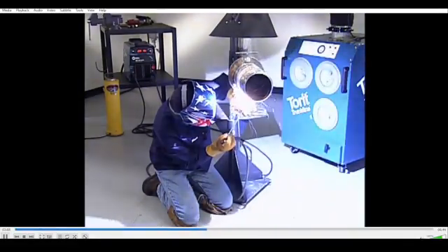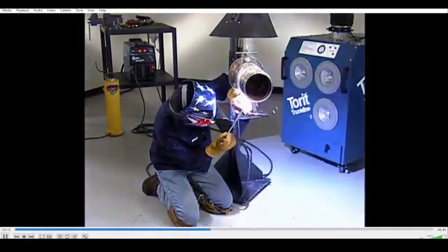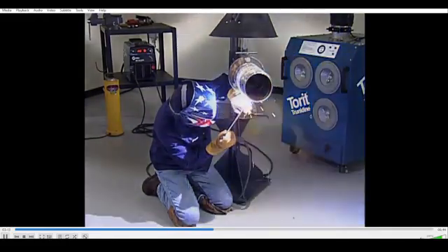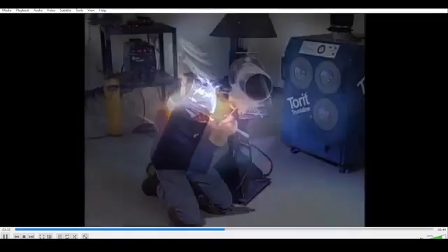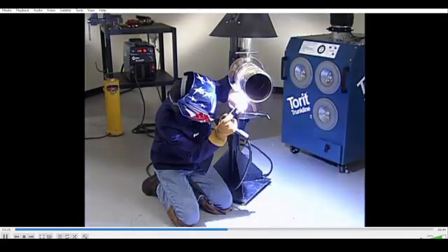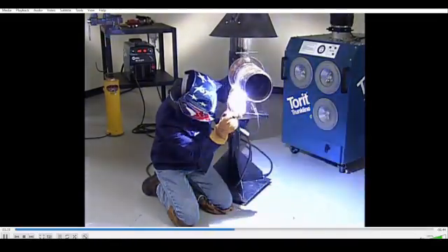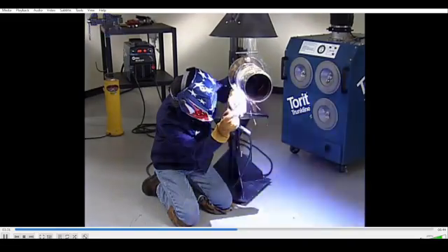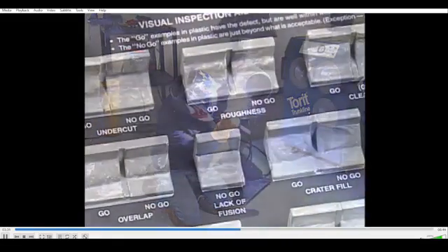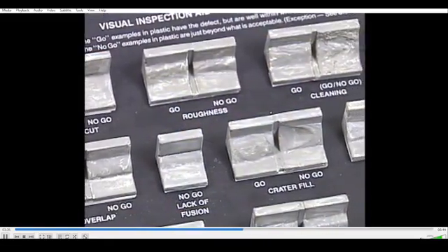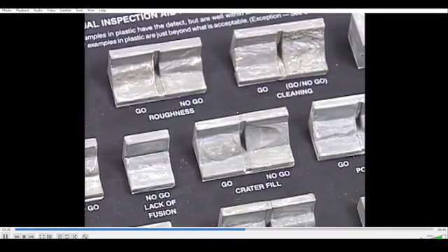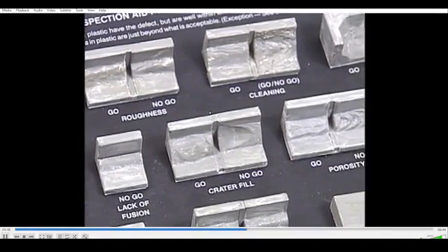The second area of visual testing takes place during the welding operation. In-process visual inspection begins with verifying that the specified procedures are being followed correctly. Observing the weld during production can help eliminate costly repairs by catching problems before completing the welds. The inspector will also be observing welder skill, verifying that proper interpass temperatures are maintained, and assuring that cleaning requirements have been met. In-process inspection might also include comparing each pass or layer to a sample workmanship standard.